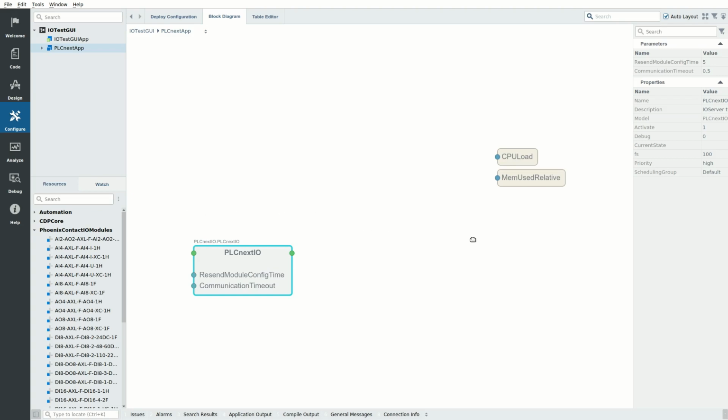The PLCnext I/O FS property decides how often the inputs and outputs are updated per second. Since no device has an infinite amount of processing power, you should set this to a reasonable number depending on your application. As we are looping values from output to input, the default 100 Hz setting is OK for our use. Select the PLCnext I/O that we added.